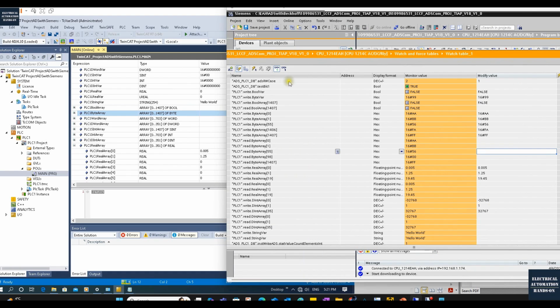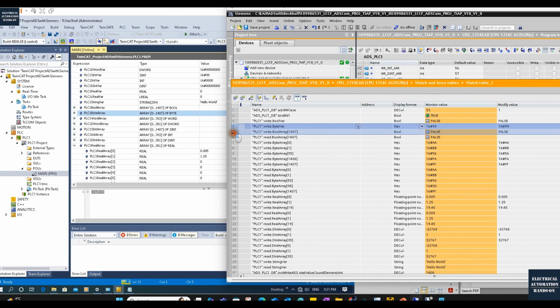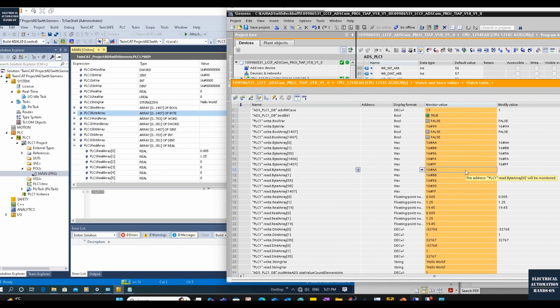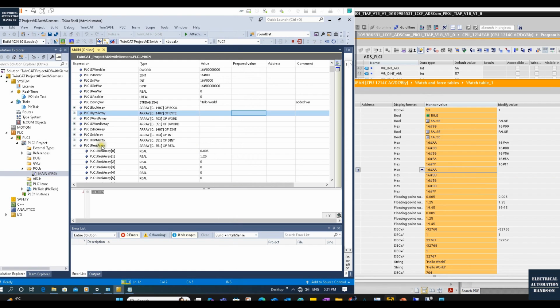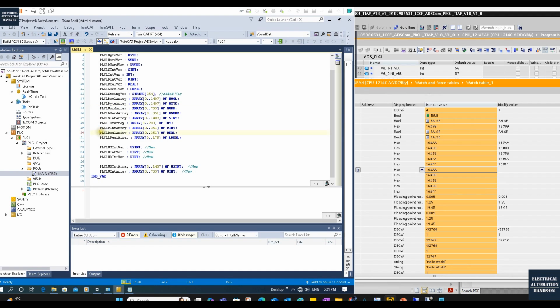All right, again, so this ADS read and write case number scrolling here is a great sign to show if the system is still live, it is working. And the mechanism from this example program is all those write areas are writing the data from the Siemens side to here and then read back. So in the real case, you read and write, typically they are separated. So you can set up separated array areas. For example, your real array can be set as a real W for write and a real R for read, separated into two arrays.